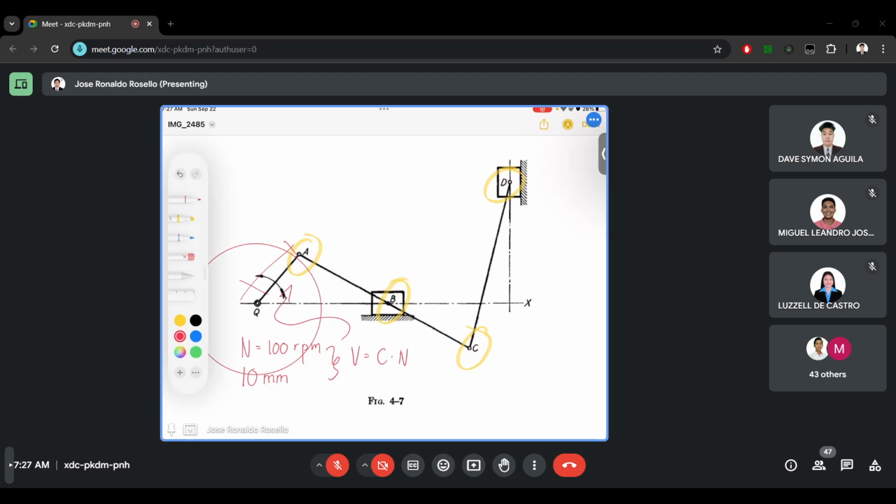So, by computing it, substitute circumference with 2 pi r, where the radius is our 10 mm, then multiplied by the 300 rpm, revolutions per minute. And since one circumference is equivalent to one revolution, we can cancel the revolution unit. We will now have 600 pi mm per minute.